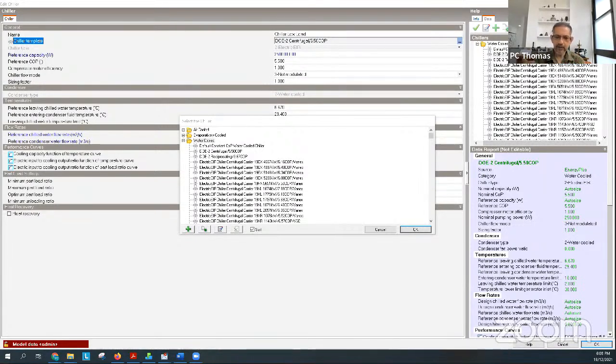I'll run the model first to look at how the cooling load varies across the year, and I'll even bin it to say, okay, how many hours does it run from 0 to 25% of the total plant capacity, 25 to 50% of total plant capacity, etc. And that gives me an idea of what I'm looking for. So on a couple of jobs, when I looked at it, from 75% to 100% of capacity, it was only using that plant for 4% of operating hours, which is a very inefficient use of plant.